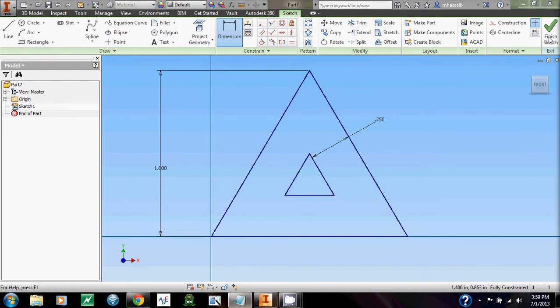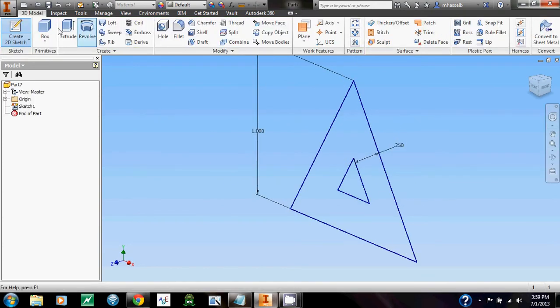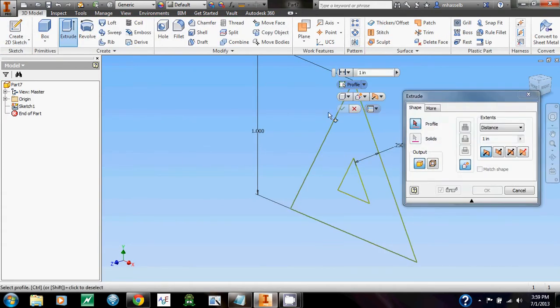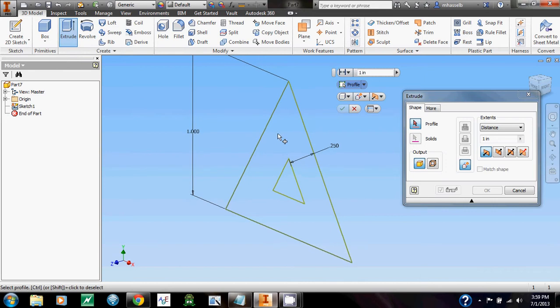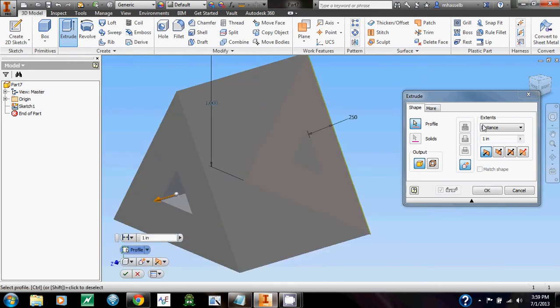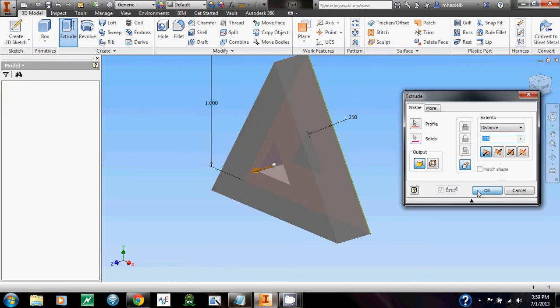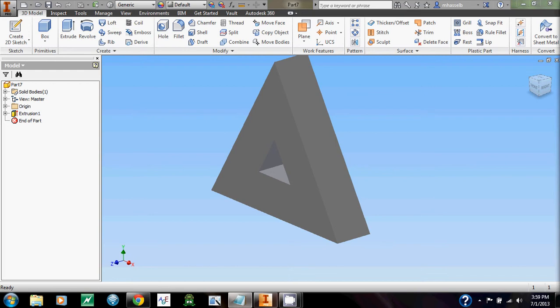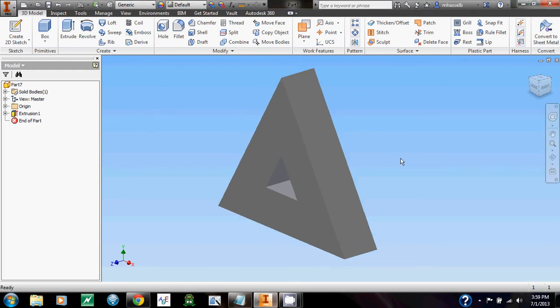So now we're ready to finish the sketch and make it 3D. Finish sketch. Now this is the extrude command, which takes your sketch and basically stretches it out, as you can see here. And all we need to do is define how far it needs to go, say another 1/4 inch. And now we have ourselves a very nice part. Let's make a new one.